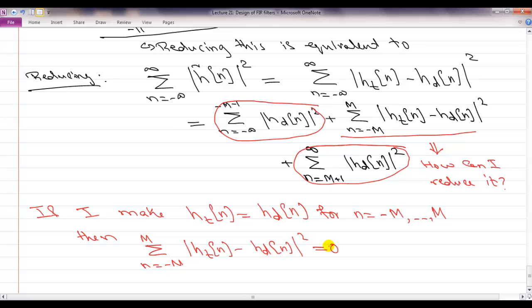Right? So how do you then design an FIR filter from an idealistic filter? Is basically you just chop off all of its pieces from minus m to m. You just keep everything between minus m and m. And we will look in more detail at what's the impact of this chopping off or truncation, or as the term goes, windowing, in terms of the frequency response.